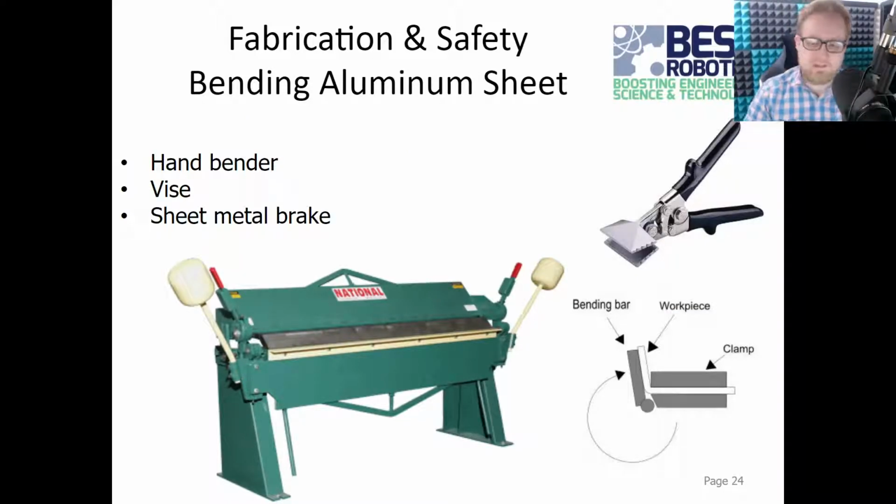Same goes for bending. There's a lot of machines specifically designed to work with sheet metal, as well as hand tools that do the same thing and can make bending your sheet metal easy. However, if you don't have access to these, you can put it in a vise and do the classic hitting it with a hammer or mallet to get the bend you want.